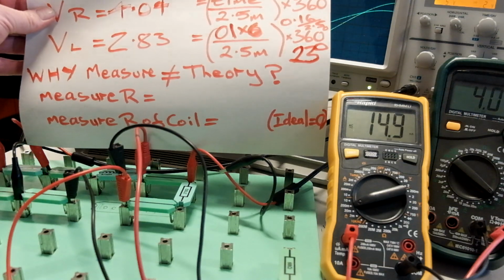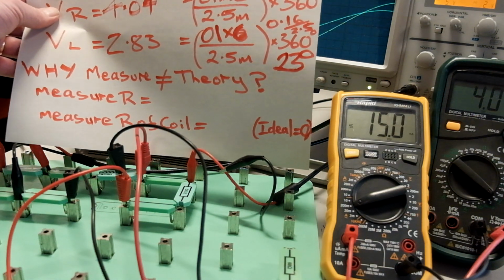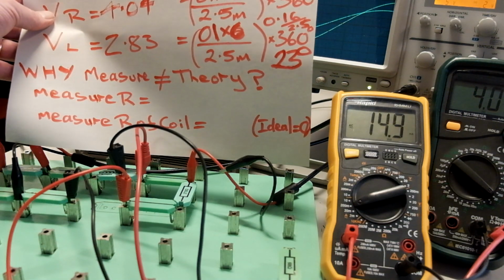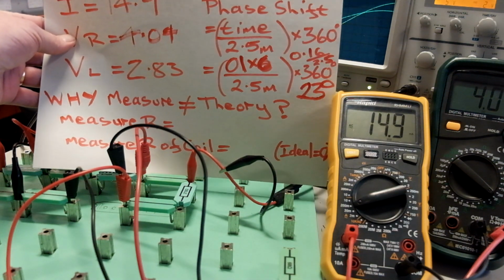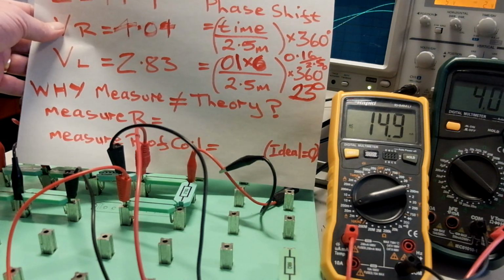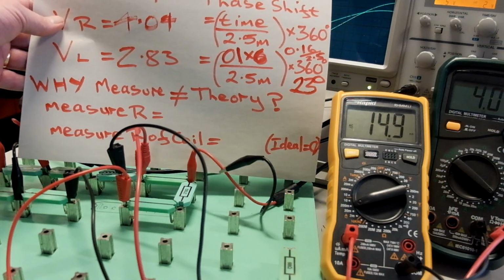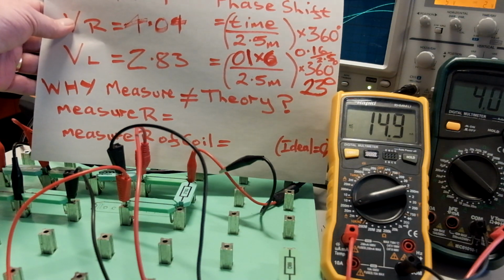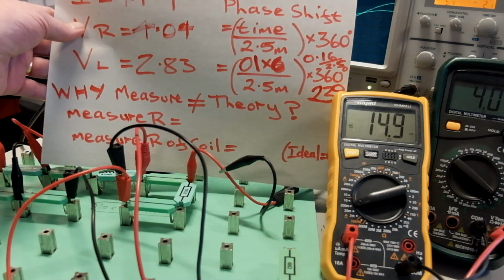Now that's fairly close to the prediction, which was 24 degrees. Not quite exact, but it's not far off. So the biggest ones, the two measurements in the physical circuit that are significantly different, are the circuit current, which is 10 milliamps out, and the voltage across the resistor, which is more than 2.5 volts out. So there's something amiss in this circuit that doesn't quite match up to the predictions from circuit theory. So what can we do to get to the root and understand what's going on?